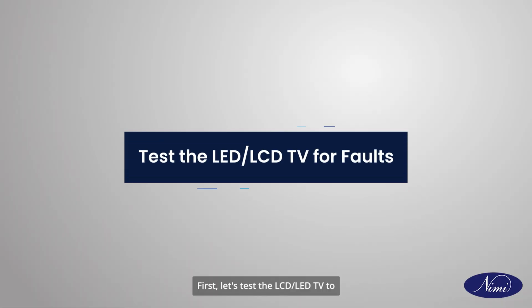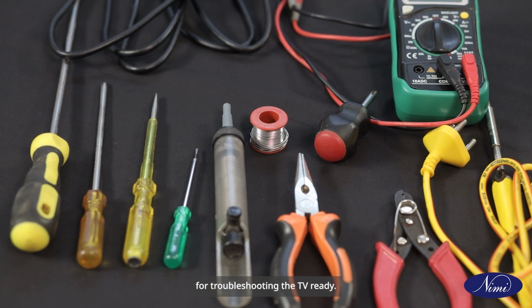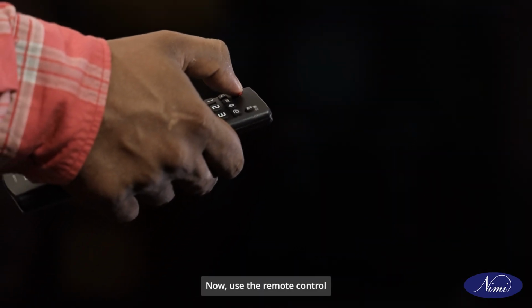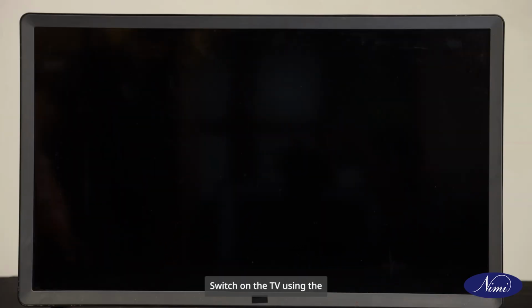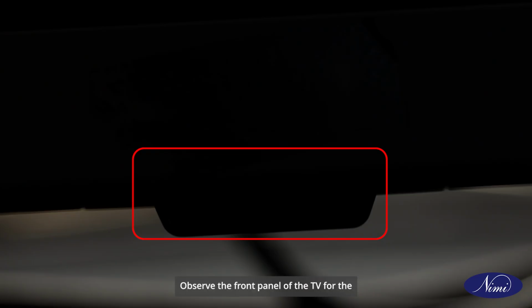First, let's test the LCD or LED TV to identify the fault. Keep all the tools and materials required for troubleshooting the TV ready. Begin by positioning the television on the testing table. Now use the remote control to power the television. Switch on the TV using the remote controller. Then check the different patterns using factory reset remote. Observe the front panel of the TV for the LED indicator. If it does not illuminate, this indicates that the television is not receiving power.